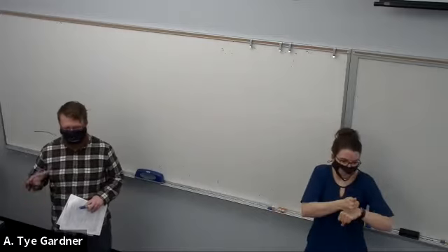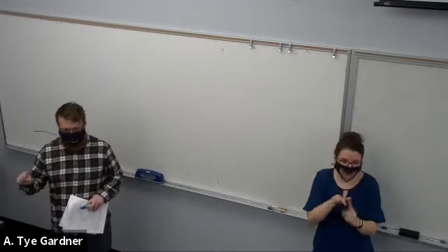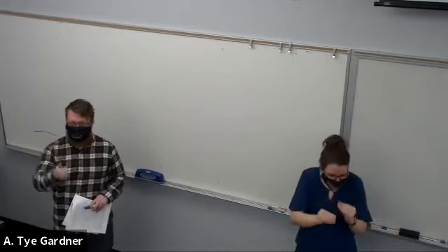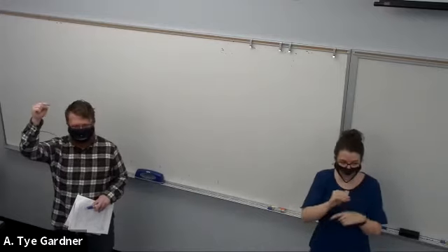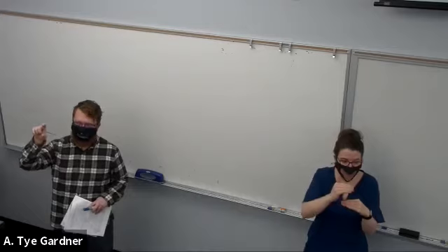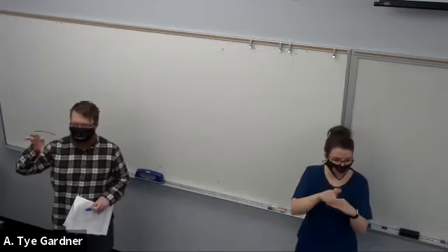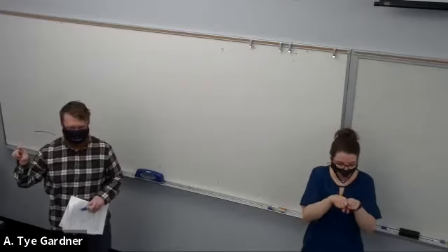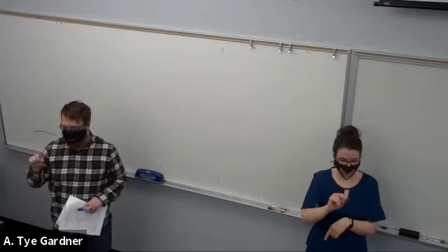Zoom is really good for this kind of problem, especially if you're running into errors that you can't debug. Send me an email with the code that's having the error, and any code that is above it in the hierarchy. So if we're designing the ALU and you're having an issue with your adder, send me the adder and the ALU so I can see how they're linked. And I also need the text from the TCL console. That way I can usually figure out what the error is from those.